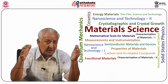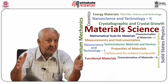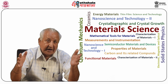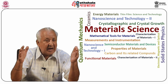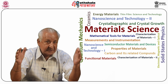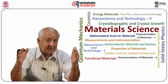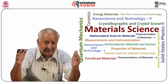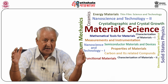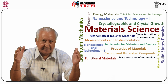Potassium dihydrogen phosphate, abbreviated as KDP, ammonium dihydrogen phosphate, abbreviated as ADP, optical grade sodium chloride crystals, and several others are grown from aqueous solutions. Quartz of optical, electronic, and high Q value grade is grown using the hydrothermal crystallization technique, whereas magnetic bubble domain materials and several useful oxide crystals are grown using the flux method.